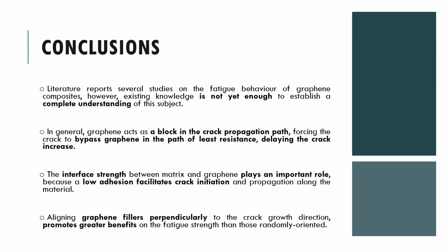Literature reports several studies on the fatigue behavior of graphene composites. However, existing knowledge is not yet enough to establish a complete understanding of this subject. In general, it can be said that graphene acts as a block in the crack propagation path, forcing the crack to bypass graphene in the path of least resistance, delaying the crack increase.